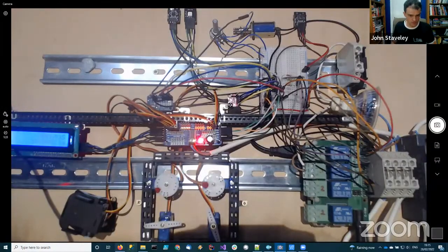Okay, so I'm going to do a quick demo. Right, so this is a continuous servo. What I'm doing is increasing and then decreasing the pulse, and that's setting the continuous servo to move either slowly in one direction or fast in one direction. So this is really quite useful for robot wheels and the like.